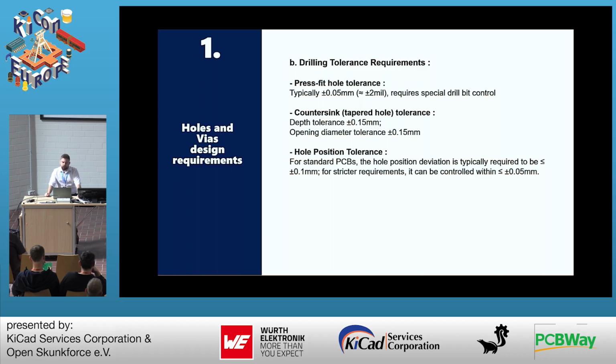When you need to do countersink or counterbore, the depth tolerance is 0.15 millimeter, and the opening diameter tolerance is also 0.15 millimeter. And for all position tolerance, the position deviation is typically required to be greater or equal to 0.1 millimeter.